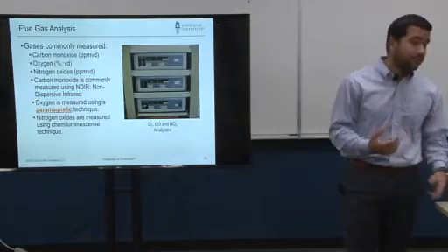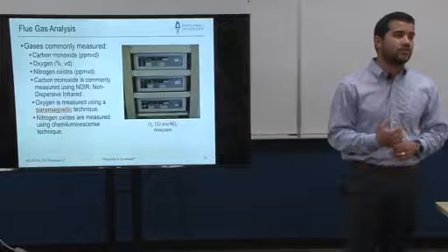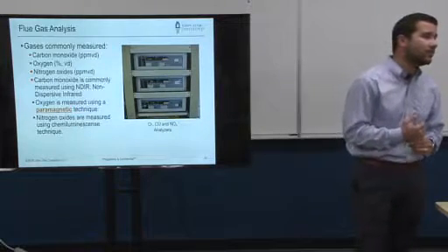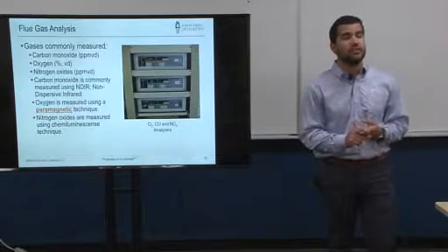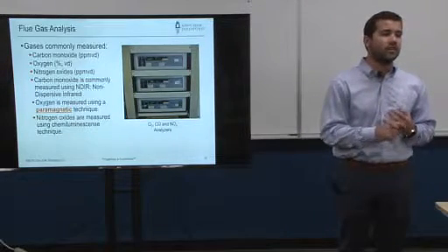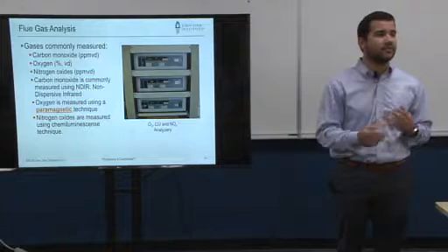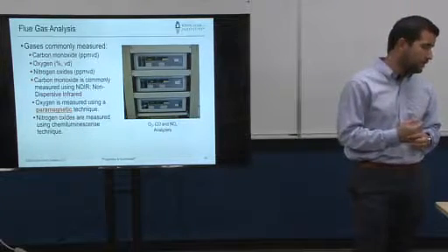And then finally, flue gas analysis. Measuring, this is the big deal of the burner. So here's where we measure the emissions of CO and NOx. And we also measure the oxygen, and it becomes important because you do some corrections with it.